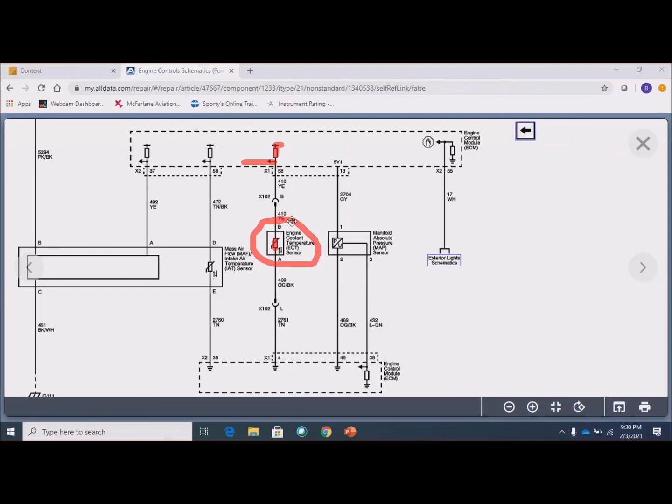If the resistance decreases on this one, its voltage drop will decrease. And the voltage drop of this one will increase. It has to, because together they drop all 5 volts. So if this drops less, then this one has to drop more.